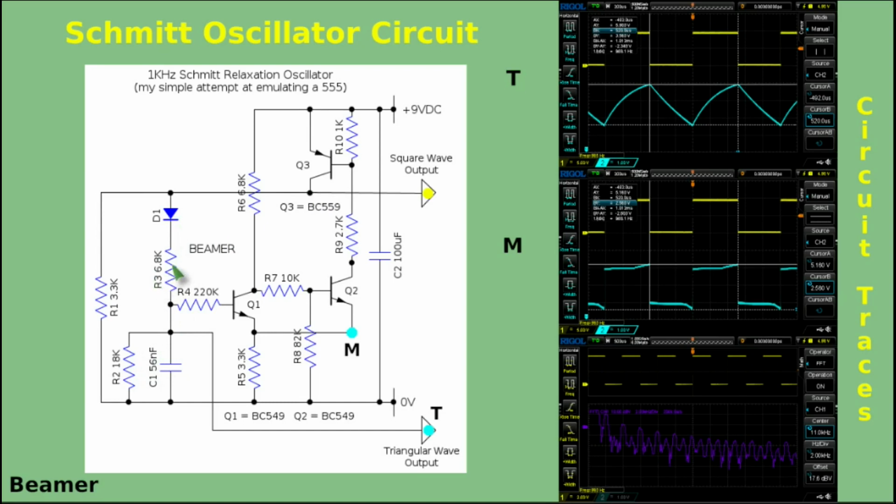So when the output's at a high, that resistor is engaged with a load of R2 across C1. But when the transistor turns off and is pulled down by R1, D1 is reverse biased, and we're left with just C1 being discharged by R2.